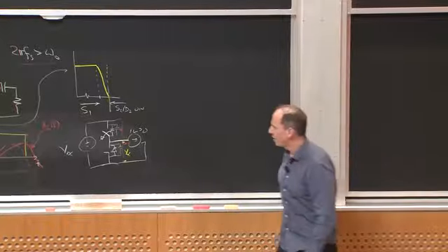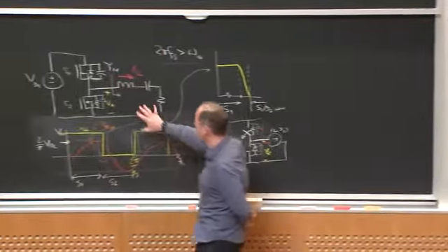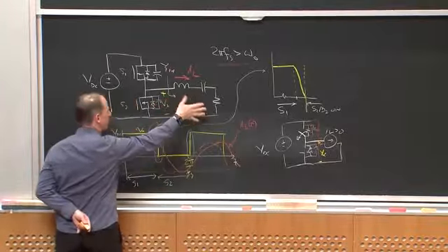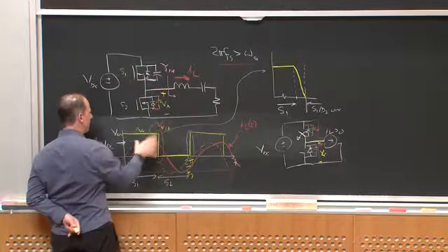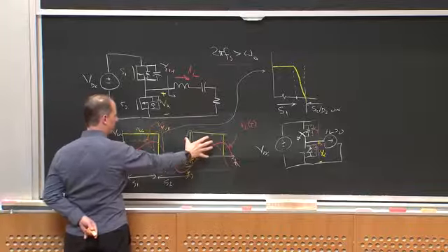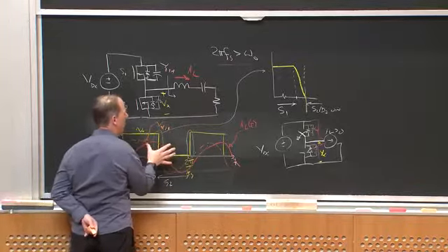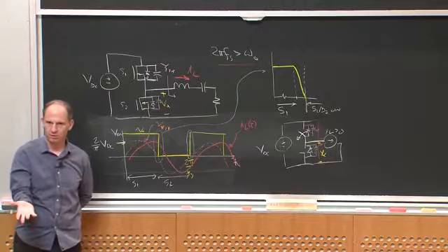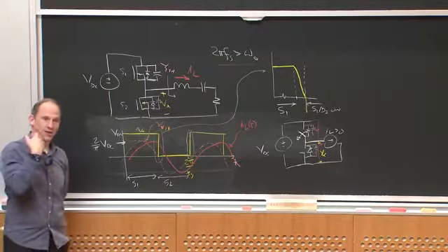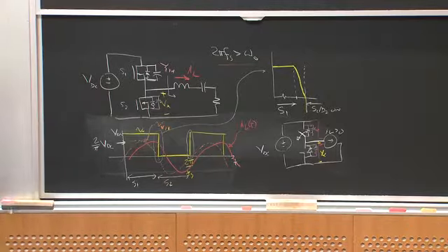So it's sort of a long way of saying, because I have this approximately sinusoidal current, and I've made it inductive, I phase delayed it with respect to where the voltage is, I get naturally the opportunity to do 0 voltage switching. So in most modern series resonant converters, because we're interested in 0 voltage switching, we will operate them up in this range above resonance by some degree and modulate power over this range by going sort of down the curve this way.